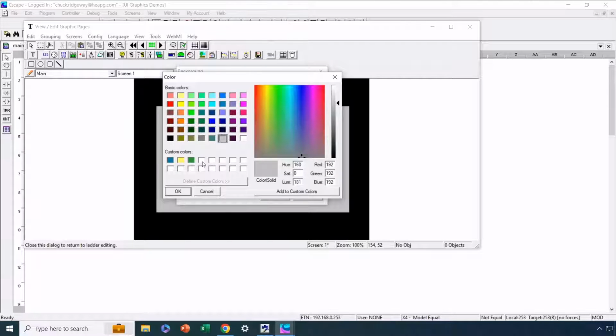So if I want to add another one, maybe based on my client specification, I click in this area here, and then I type in the red, green, and the blue parameters. Okay, so for the color I want to add here, the red element is 232, the green is 27, and the blue is 84. And this gives me a very specific red that the client wants to use.